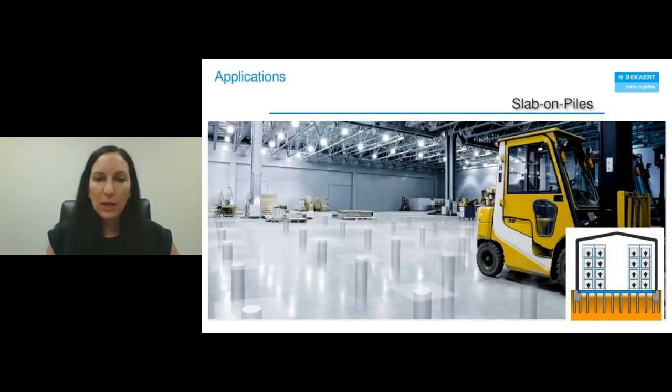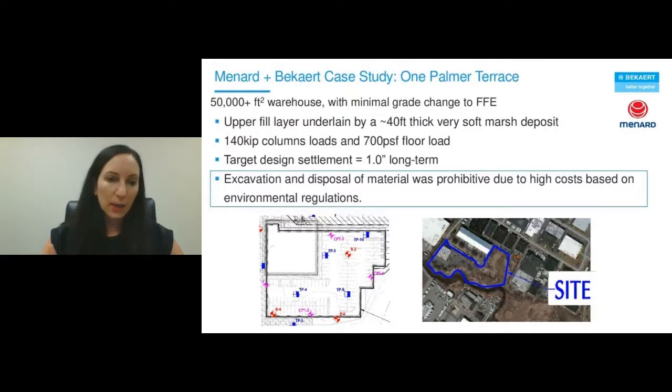So because of the 5D fibers that we have, those structural fibers, we can provide a structured slab approach for these discretely supported slabs. Now, these are not technically a structural element in the sense that they're not supporting the building above, but they are structured spanning from support to support. And so we do have to count on the real strength and the strain hardening performance that we can get from the 5D fiber.